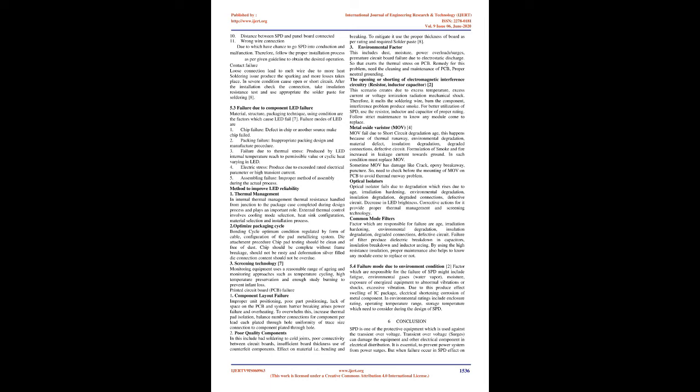8. Serviceability/accessibility. Failure occurs if services or maintenance are not performed, i.e. non-replaceable modules, batteries, or other components. So, need to do yearly maintenance. 9. Residual current device. Fails to operate due to wrong trip setting and improper earthing, and produces unwanted tripping. To overcome this, follow the trip setting and earthing as per guideline.